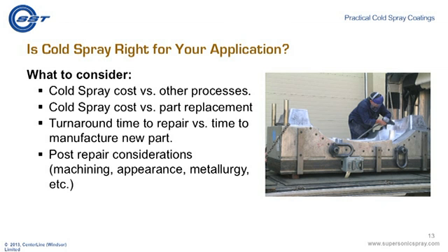Well, you want to compare the cold spray cost versus other repair processes. Obviously, you want to compare the cold spray cost versus part replacement, and that's where the value of the part becomes quite important. The turnaround time to repair versus the time to manufacture a new part and the costs associated with that. And any post-repair considerations.